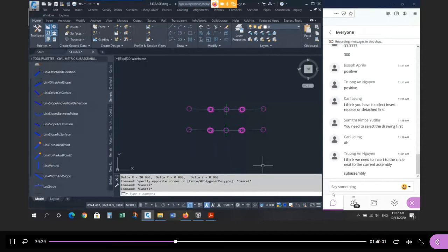Didn't go as smoothly as I had hoped. I usually like to change the dimension before I draw the item. So I want to draw 385 at -2, put it in the drawing, then draw the gutter dimensions, and then put it in the drawing and so on. If that doesn't work for you, like the problem I just had, just create it so you have something and then revise it. Okay, any questions about that?